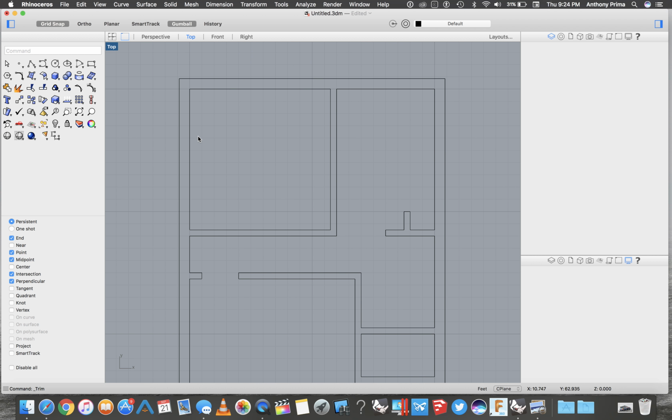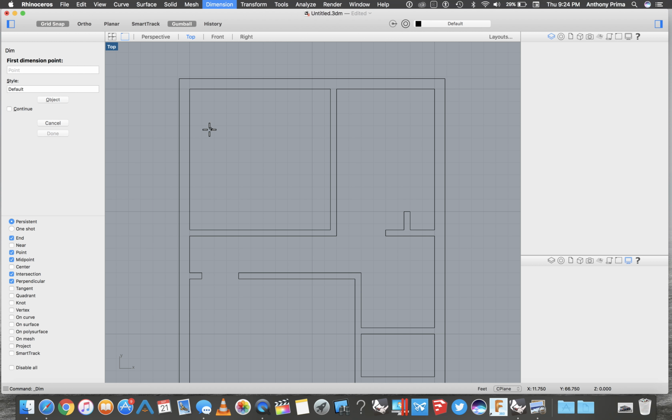One thing that really helps with using the rectangle tool is you get really specific measurements. So this one originally I made it 12 feet, but then I also had the 1/2 foot partition. So this one should be 11.5 feet by 11.5 feet. And I can check that with the dimension tool too. I'm just going to go ahead and snap that there and there, and we have 11.5 feet.